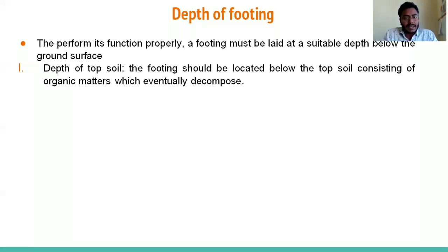So we have to select the depth of the footing by keeping all the factors in mind, so that the bearing capacity that we have taken for design would be the same, would not vary throughout the life of the structure, right? So by keeping all these factors in mind, we have to select the depth of the footing.